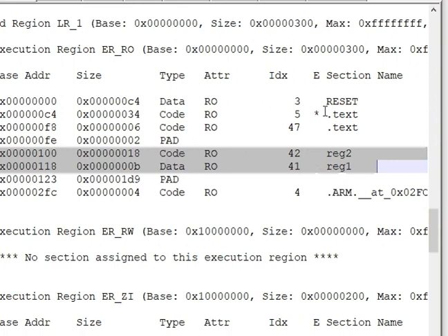Along with that, there is the startup file, which you are also supposed to use. All of these have different addresses, and these addresses cannot be relocated. You cannot modify them, and the same addresses are going to get into the memory of your IC. That's the job of a linker.